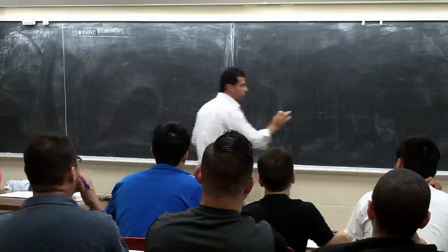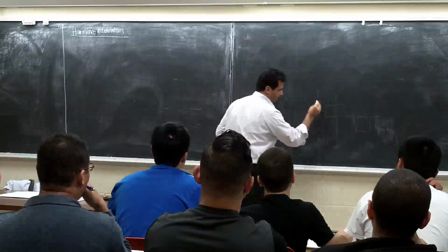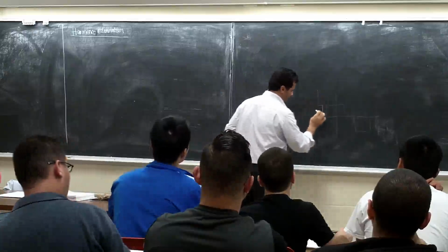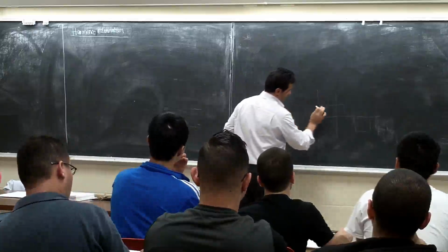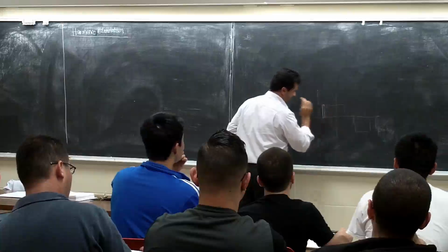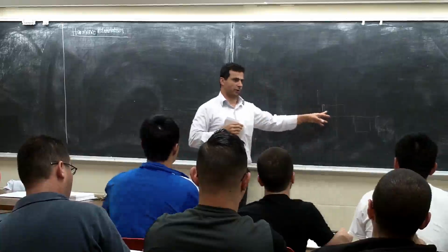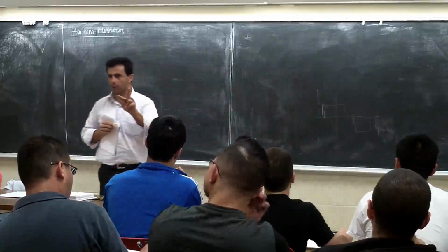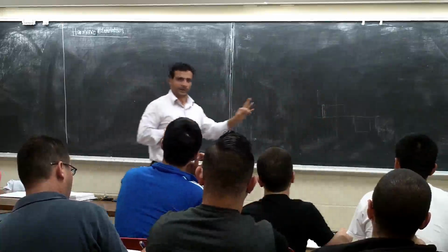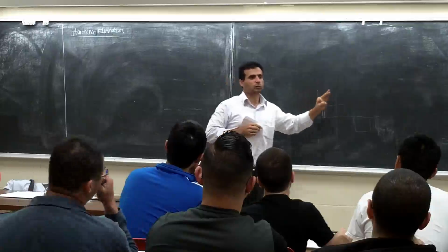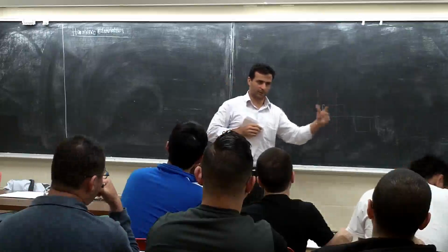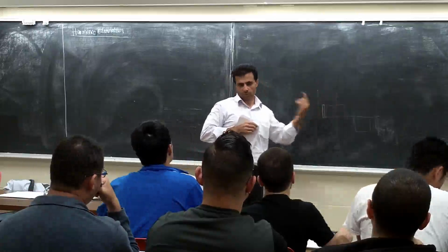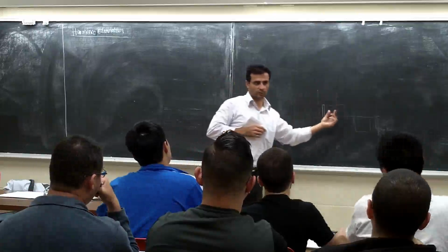But if I have 2 notches for some reason, for example, I have something like this, right? Like this. Now I have 2 notches, right? So I can do 2 things. For example, I can eliminate third and fifth, or I can eliminate third and control the fundamental, you know what I'm saying? Because I have 2 parameters to control here. There are 2 parameters we can control.